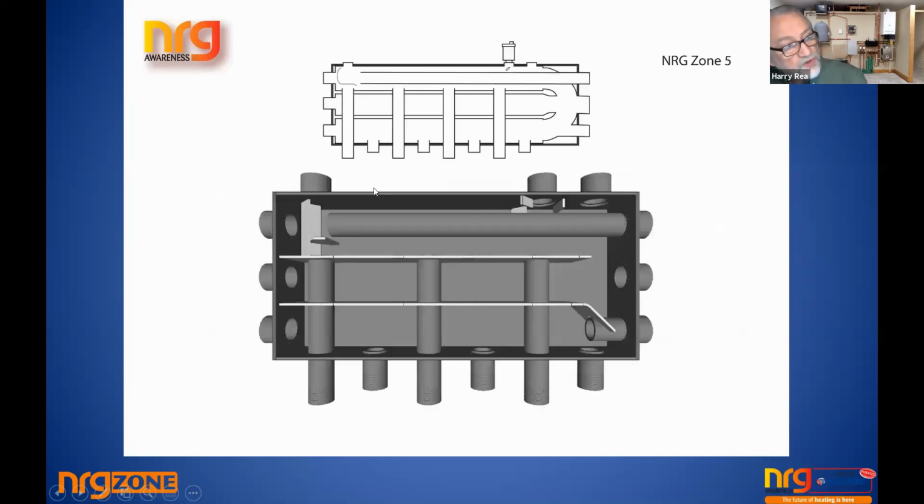So when I showed you the diagram, I was referring precisely to what's going on inside. It's exactly what's in the diagram, but you can see this baffle that breaks the water up and prevents that water reaching over to that socket and prevents the water coming in here from reaching that. You see this shelf here is to stop that water so it won't go down the zone. And it causes part of the more turbulence here that causes the air to rise. There's a funneling area here that captures the bubbles traveling along, and there's a block that catches the air here, and you find that it releases the air in the system extremely quickly.